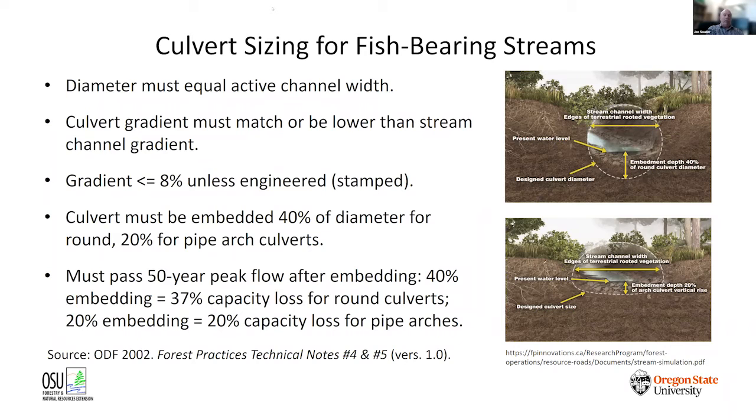The other thing to consider, and it's too complex to really get into right now, is that once you get above maybe a 6 or an 8 or a 9 foot, certainly a 9 foot culvert, you might be better off looking at an alternative, like either a half pipe with concrete stem walls on top of it, or bridges. There's a lot of interesting designs out there for bridges now that resolve a lot of these problems with larger culverts. And at some point, probably the 6 to 9 feet, the cost calculation changes so that a bridge can actually end up being cheaper than a culvert.